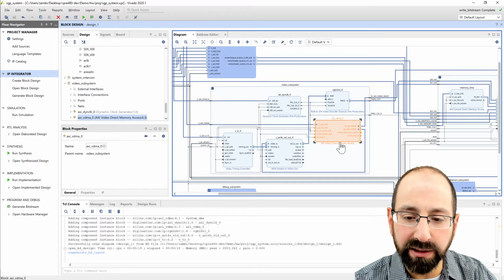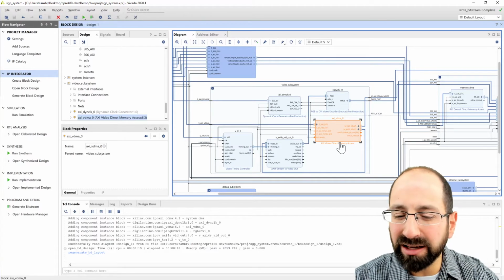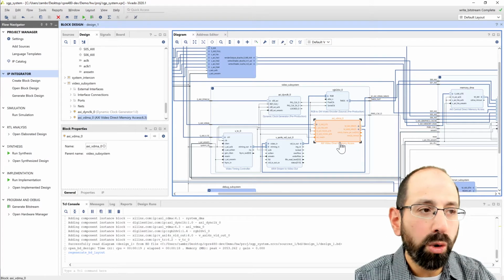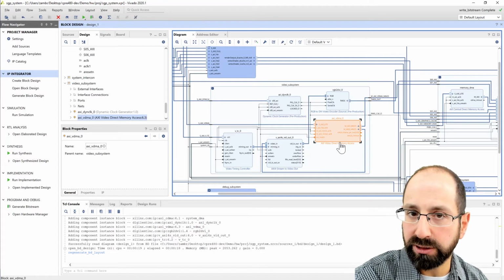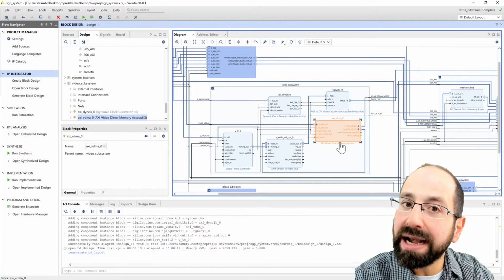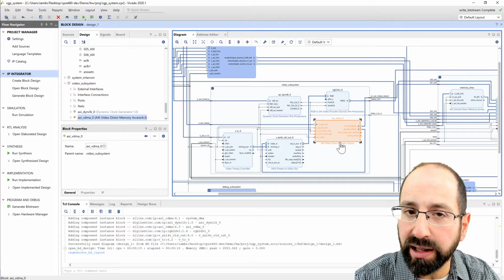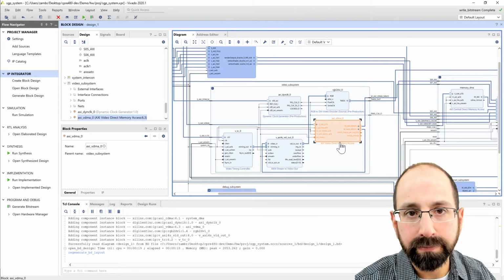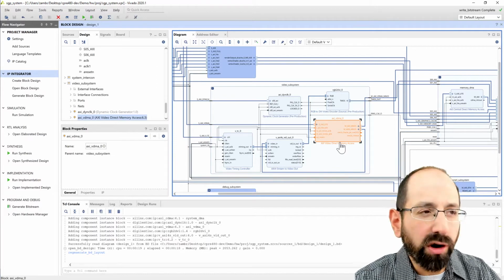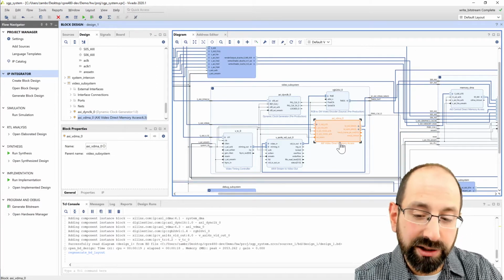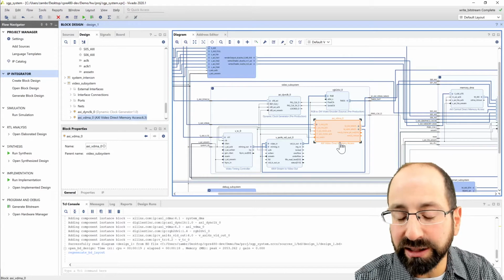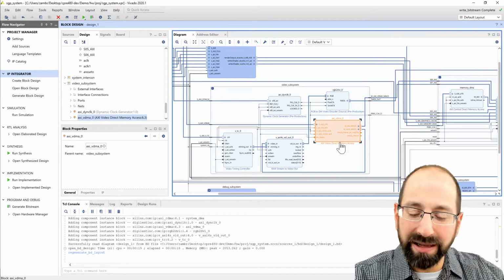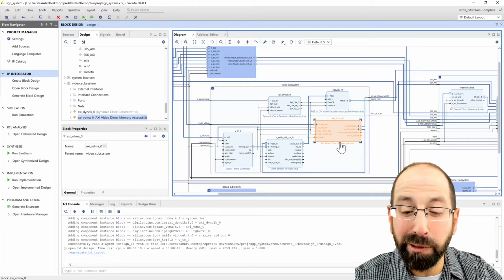Think about it from this perspective, right? We talked about the double buffering. We didn't talk about all the details of that, but how there's two frame buffers logically in memory. One we're always reading from to display the screen, and one we're writing to update what we would like to display on the screen. And the reading process should always have higher priority in a fixed fashion. If our writes are slow, if we're not writing to memory as fast as we would like to, we're going to wind up having effectively dropped frames. Our app isn't updating the screen as fast as we would like.